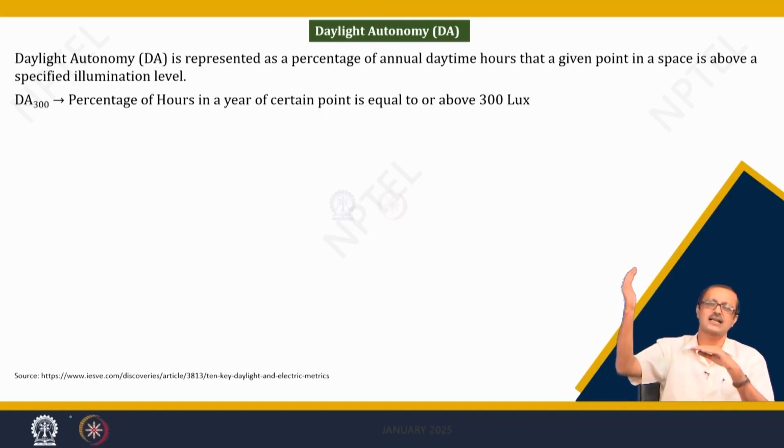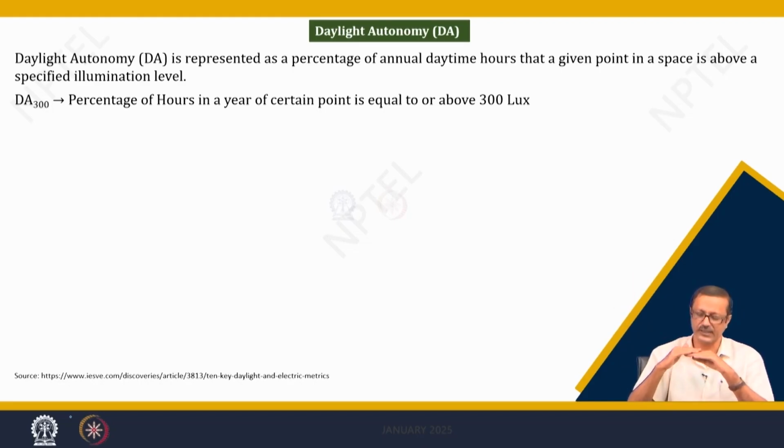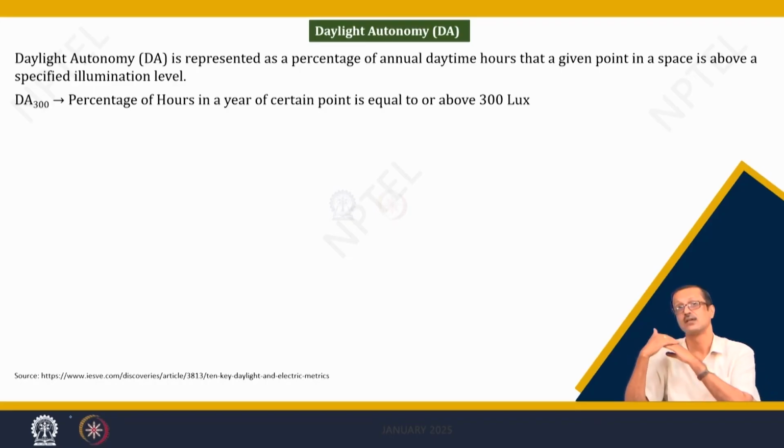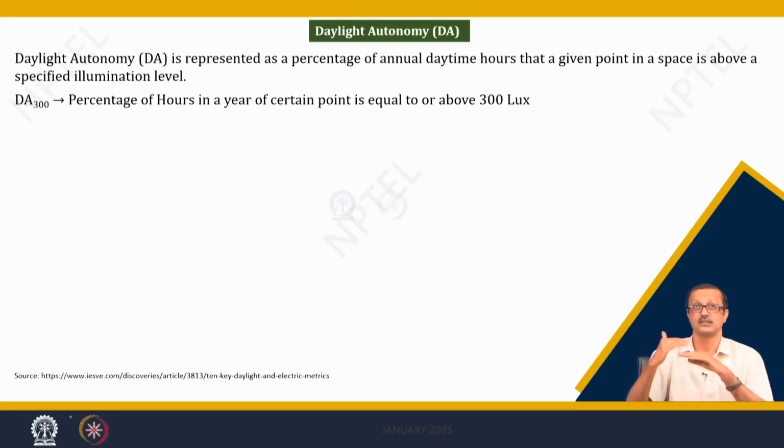Based on the sun angle, this particular point in the interior will not have constant and similar daylight throughout the day. Morning it may be less, evening it may be more if the window is in the western part, in front of that. If the window is in the eastern part, the morning will be high and the evening will be very less.